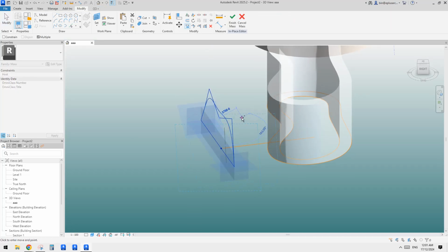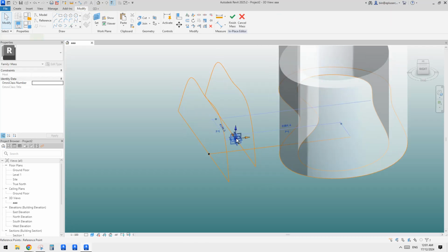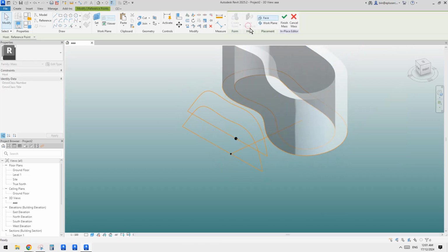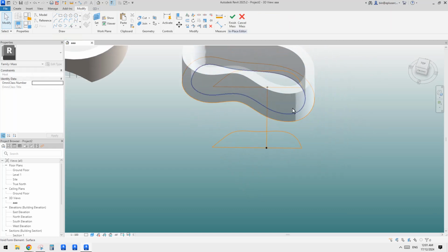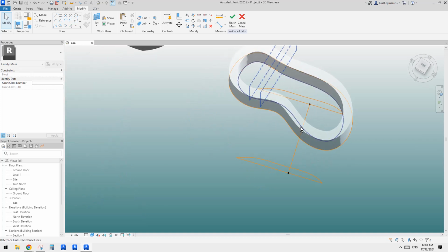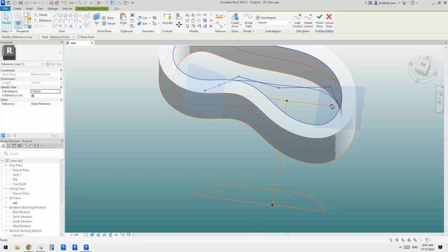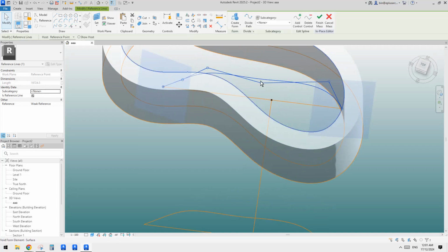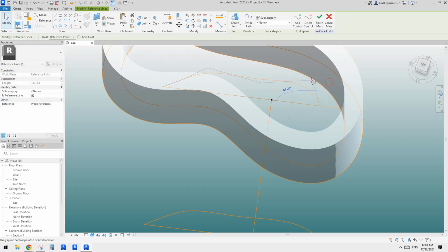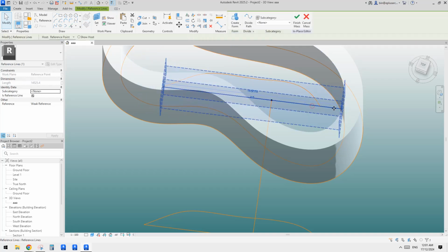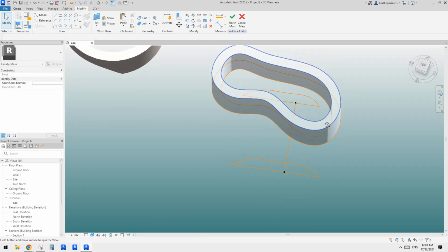So, and then copy everything we have, the points, and then two reference lines. So select this point, and then we use pick new host, then we pick onto the other end. Okay, and then you just need to manually adjust this. So for example, I try to keep the height again, so I'll use tab and drag this one, right, and also manually drag this one horizontally, and then drag this one to this end. So yeah, I think that's probably it.